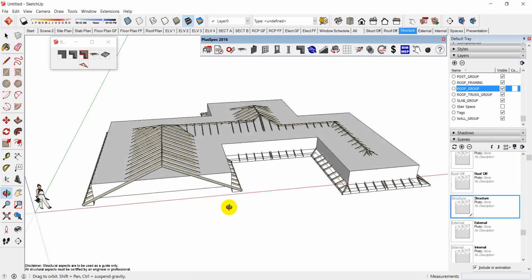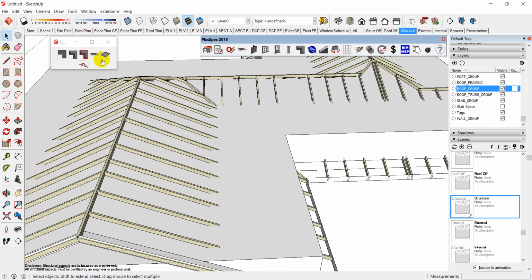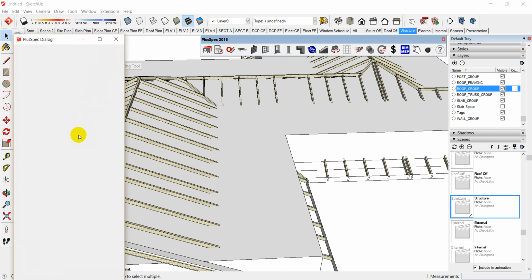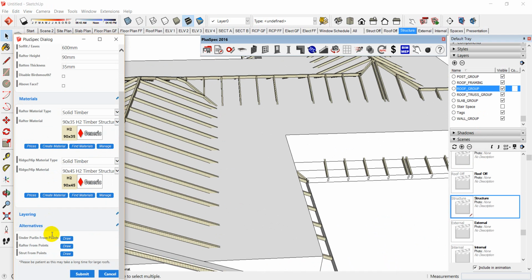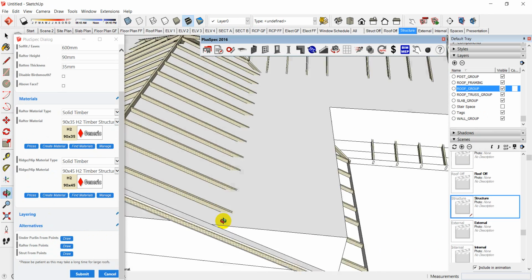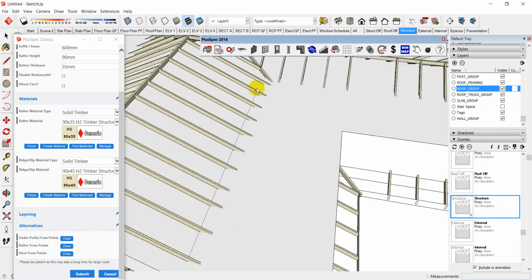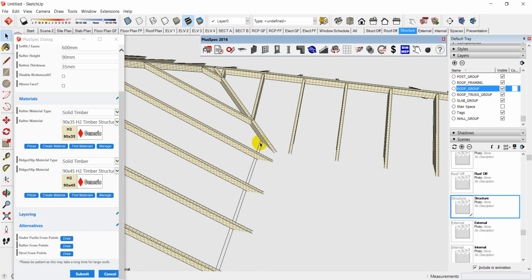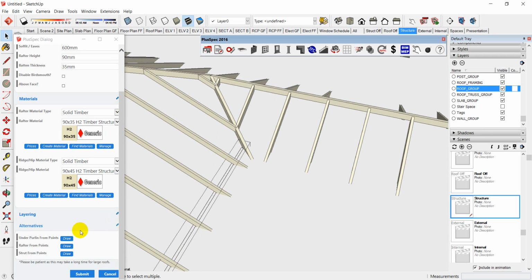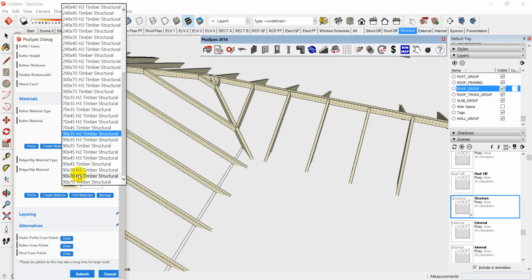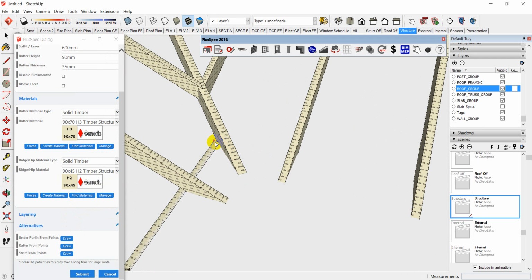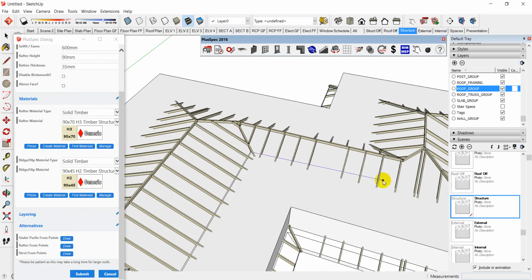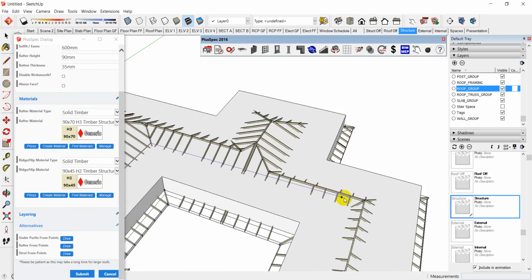Okay, so we go to structure and I needed to turn roof underscore group on. There we go. Now when I go and do my under purlins, I would just simply go back to my roof framing tool, and down the bottom you have a whole heap of different options in alternatives. So under purlins, you might simply say, okay, well, this is an overhang out here, so I want to do an under purlin from here to here, and you might say do the same, go draw, and these are judging the sizes, so usually you might have, say, 90 by 70. I would be interested in talking more about this with you, probably not for everyone because not everyone's doing roofs. Under purlins from here to here.